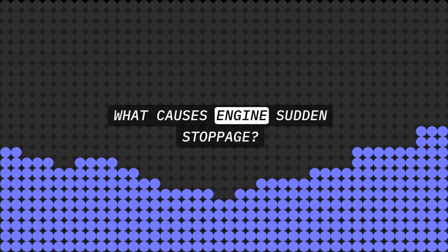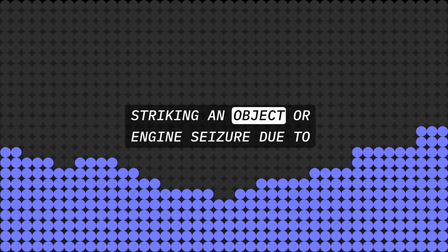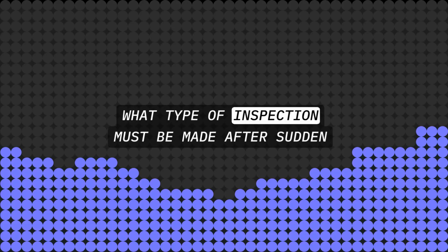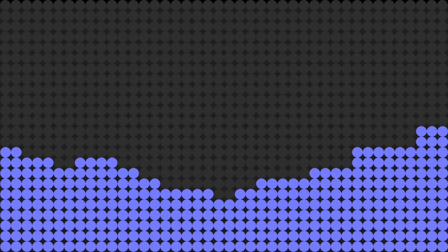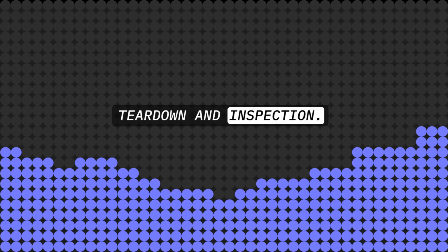What causes engine sudden stoppage? Striking an object, or engine seizure due to internal damage. What type of inspection must be made after sudden stoppage of an engine? Most manufacturers require complete engine teardown and inspection.